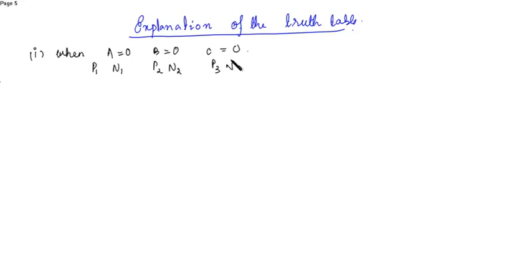We'll see the twisted schematic later on. This is P3 N3. The input, if it's 0, then PMOS turns on and the NMOS turns off. When input is 1, the PMOS turns off and the NMOS is on.